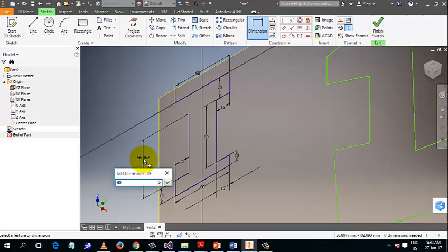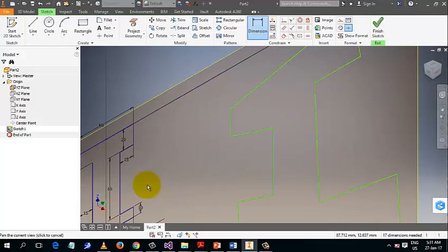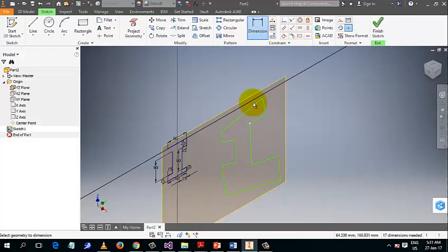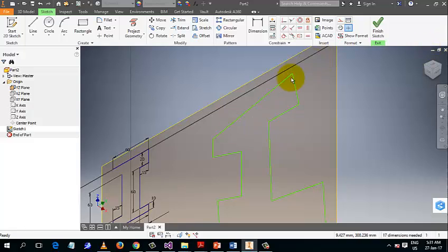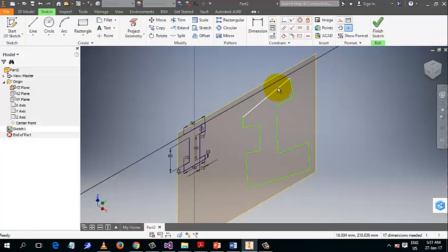So the same thing can be done here. You can try to make this horizontal. It's not horizontal. So you click on the line. Before you start, the escape button is always right there, to exit a former command to start a new command. You click on this line, then you click on horizontal. You see that it's aligned horizontally, and it's also constraining others because they are joined together in a way. Then you can use dimension constraint to make it 60.